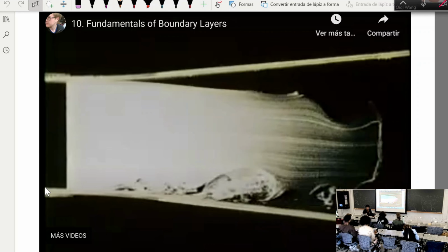And that's actually one of the reasons there is a lot of difficulty in actually getting flow to be laminar on real airplanes. Because if the real airplane just hits a bug that attaches to the leading edge, that can destroy your whole effort of making the flow as laminar as possible. So it's really easy to trip the boundary layer to make it turbulent. And in this case, the upper surface is very clean; it stays laminar. The lower surface is tripped to turbulent.